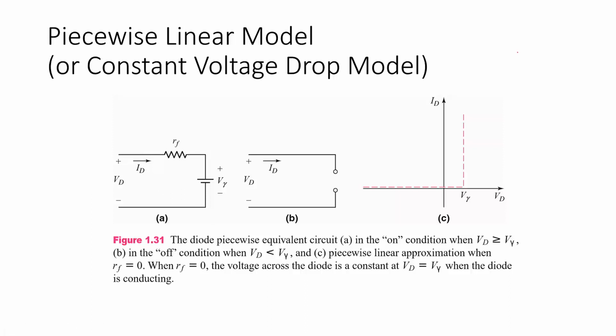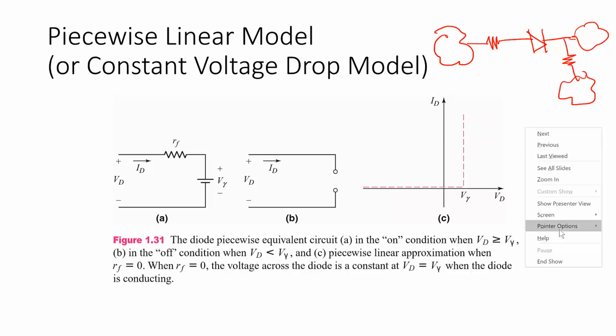So using the earlier example, let's say this one is connected to a resistor, a diode, and a different resistor. Each goes on to another part of the circuit. If it is reverse biased, this will just be an open circuit.